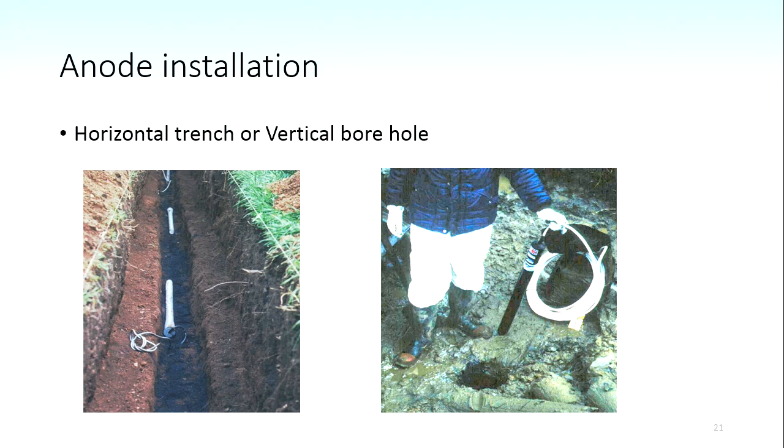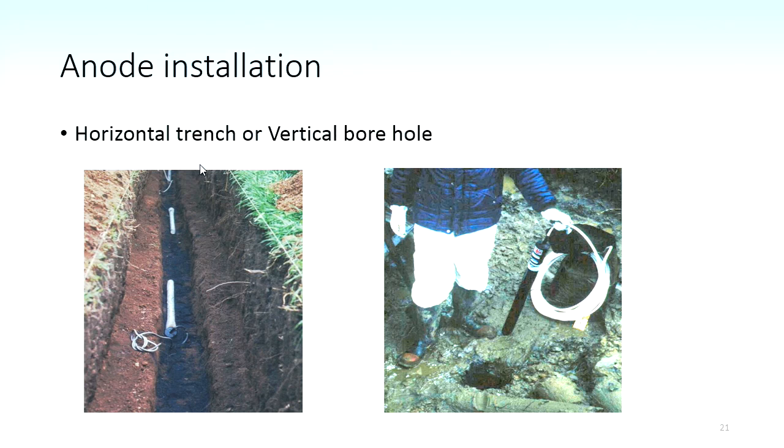So they increase the conductivity of the trench by adding carbon, effectively, and coke is cheaper than a lot of other things, so you just backfill the whole thing with a cheap supply of enhanced conductivity material, and that allows you to get a better potential distribution and current flow. Okay.